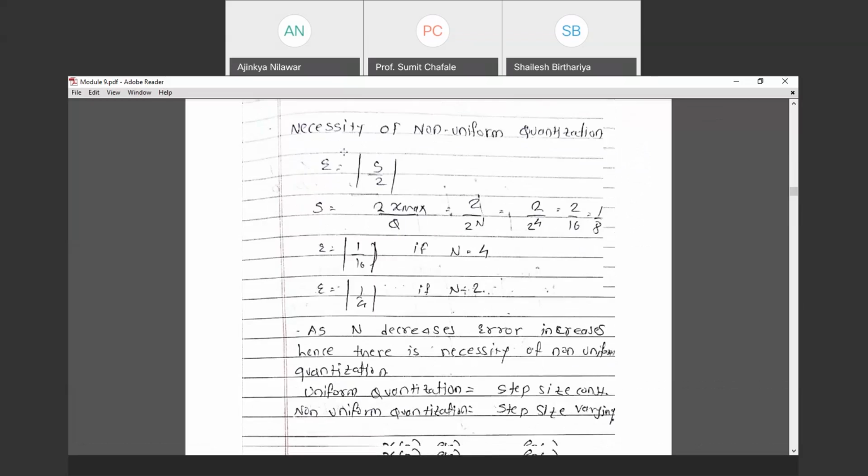Again, I am just explaining with the help of a waveform. Consider this sine wave, and whenever this wave gets cut by our quantized signal. So a simple block arrangement is there: sampling, 1-bit quantizer. In PCM and DPCM, the quantizer bit is not mentioned there. That is n bits. N bits means 2 raised to 2, 2 raised to 3. So in the delta modulation scheme, we have only a 1-bit quantizer and the output is definitely only a 1-bit representation.